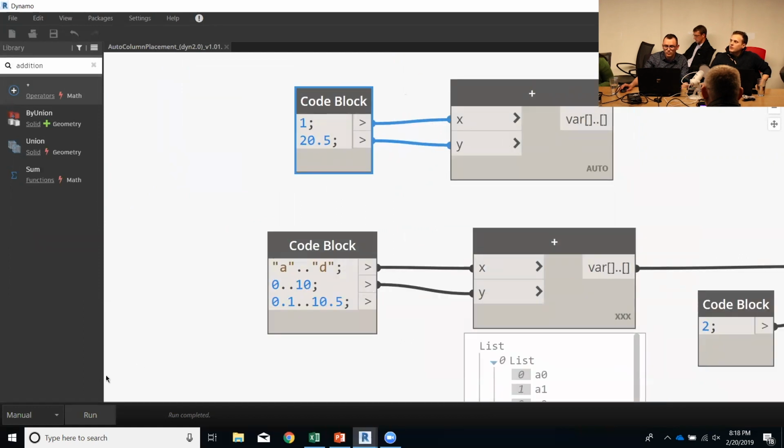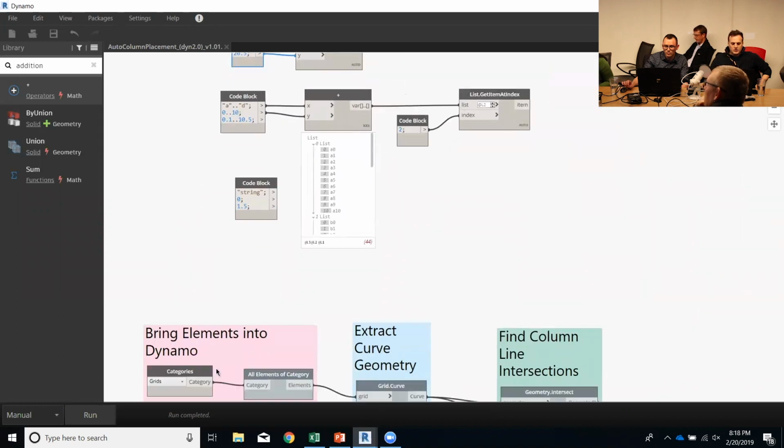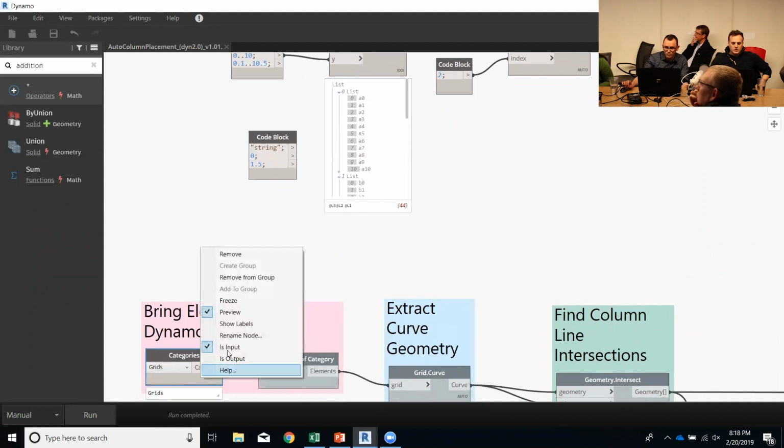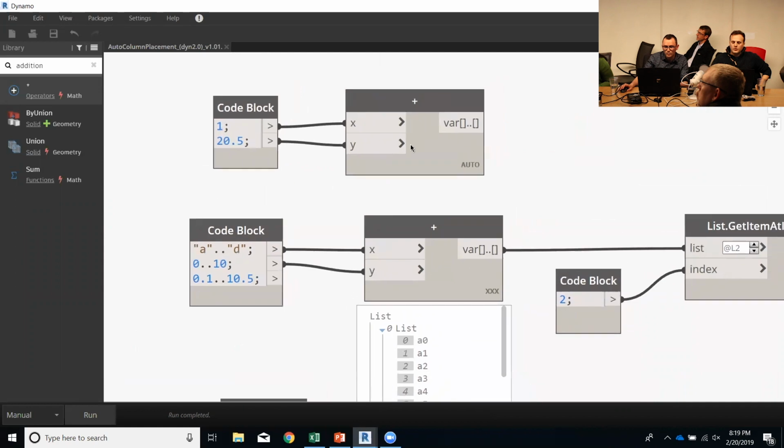And you'll see there's something really nuanced going on in my script here. I have this set to manual. If you're developing a script for someone else's use, it's really important that you set that value to manual. Because when they open your script for the first time and it's set to automatic, it will start running, and if it's a really complicated script, that could throw some really big issues. So, not knowing where everyone's at in the room as far as skill levels, I wanted to introduce these basic concepts because we'll be building on top of this as things get more and more complicated.